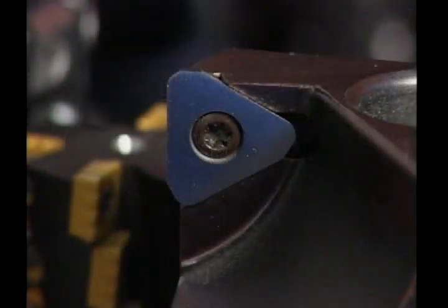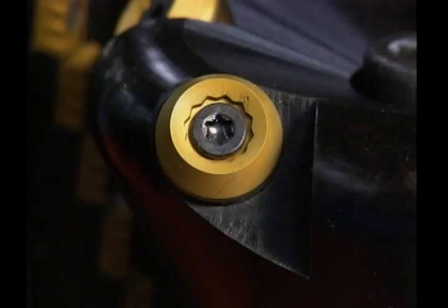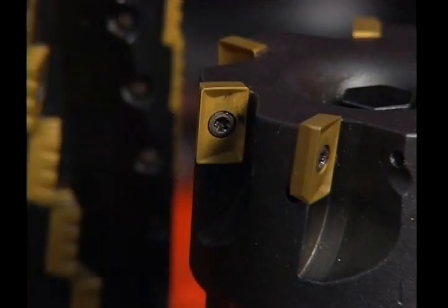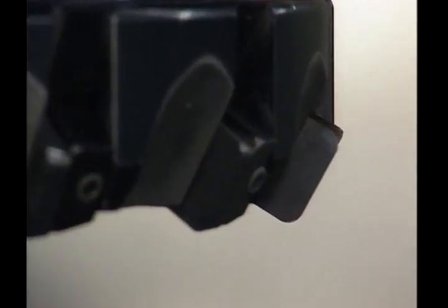Milling inserts are available with various grades and shapes. In addition, milling inserts have their own corner geometries, including the radius and the wiper flat. A large corner radius produces a finer finish than a small radius, but a corner wiper flat on the insert produces the finest surface finish.